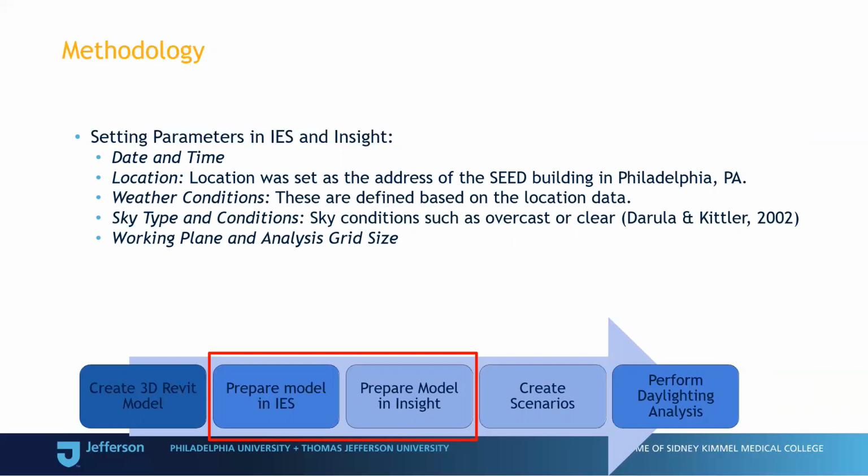accuracy of simulation. Selection of the analysis grid and specific nodes within the grid work plane allows hourly luminance values to be calculated over a year in case an annual daylighting simulation is performed. A specific node can work as a daylighting sensor, especially in Insight due to its link to the Revit file. It is possible to draw an analysis grid to perform daylighting analysis in a specific area, as was done in this study.